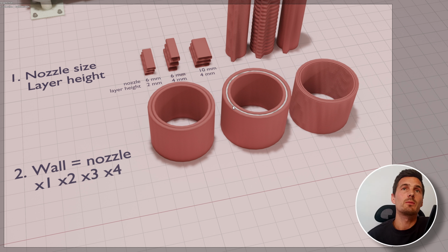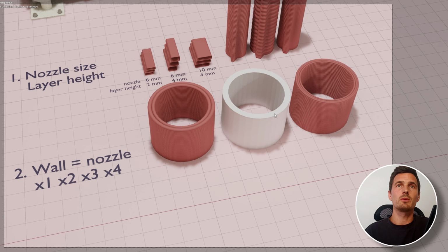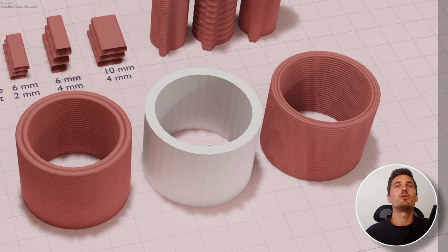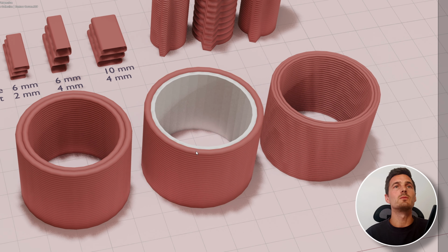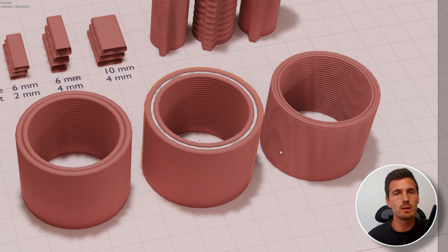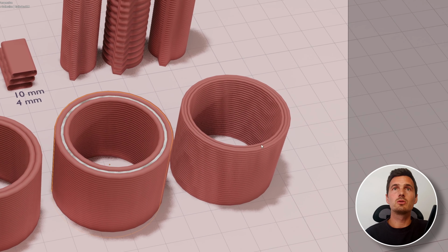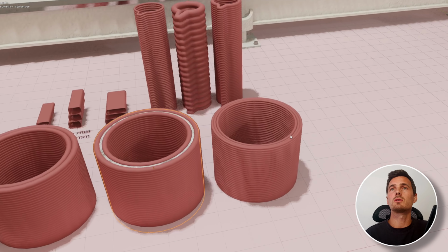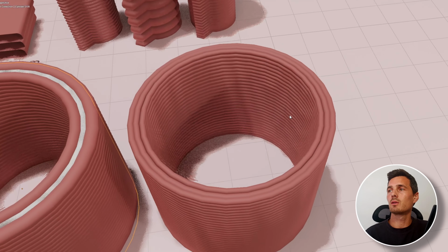If you are going to design an object of 20 millimeters, for example this object, then you have to be aware that you cannot use 2 contours of 8 millimeters, because then there will be a little gap in between, and that's something you don't want. So then you have to consider using one nozzle of 10 millimeters. Or, if they don't have the option of 10 millimeters, you have to consider reducing your walls to 16 millimeters. What you can also do is use a smaller nozzle and create 3 contours.